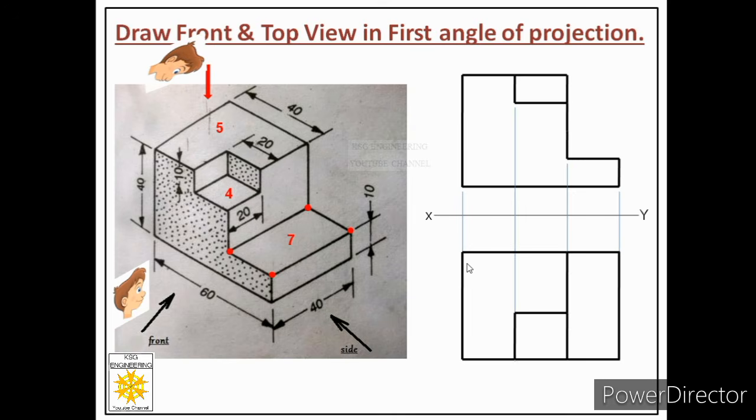So let us first place the height of the object. So how much is the height? Height is 40. So from these 2 points, draw continuous thin lines by leaving 1 millimeter gap and draw a dimension line after leaving 10 millimeters gap from the object line. Place close filled arrowheads on both sides. Arrowheads must touch the extension line and you can follow any system of dimensioning. Over here I am following the aligned system, which means vertical dimensions are readable from the right side of the page.